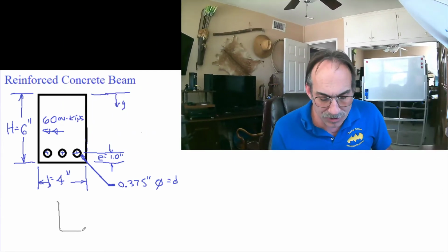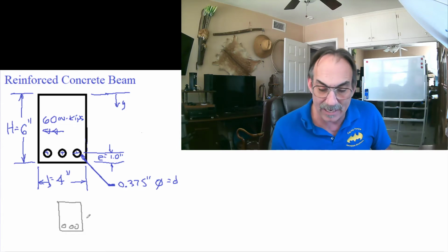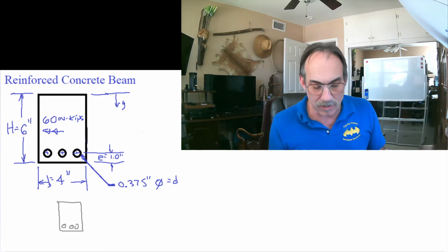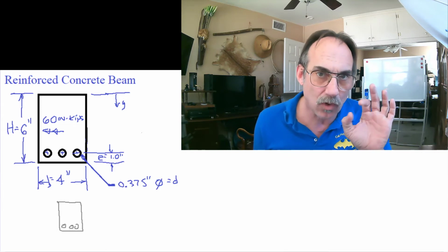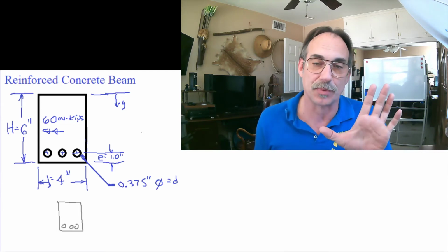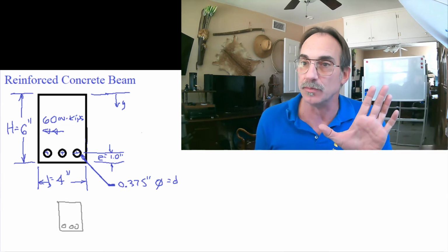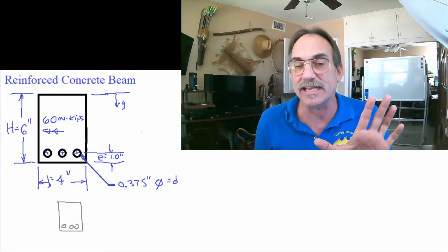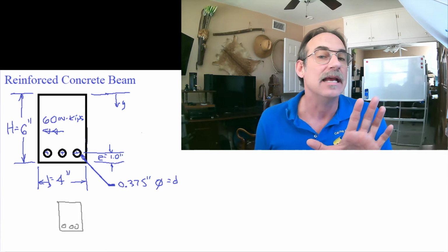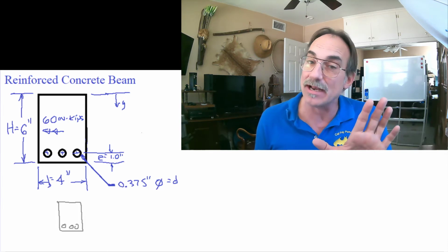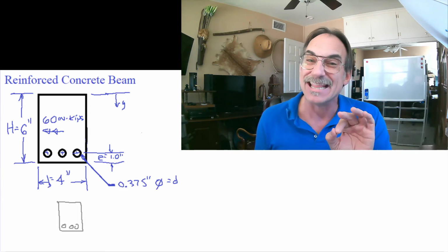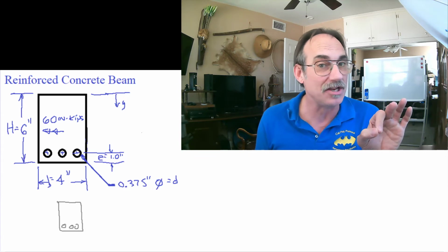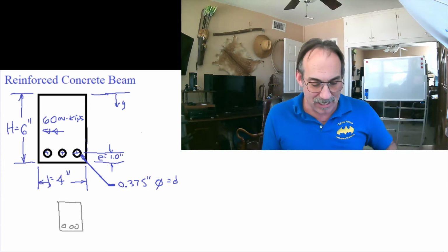If our original section looked like this, and it did, we're going to apply a typical concrete analysis procedure, which basically assumes that the concrete, which is really lousy in tension, is completely cracked. And in its cracked state, it can carry nothing but compression. That's what makes this problem challenging for the average analyst.